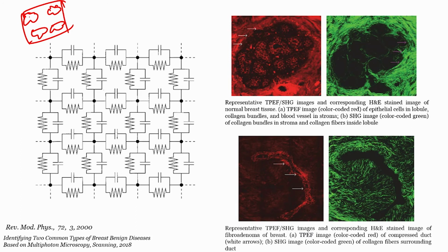You would agree that this conducting island can be considered as a finite resistor element, because it can be considered as an analog of a metal wire, right? In between there is a non-conducting region. This non-conducting region does not conduct electricity, but it can act as a dielectric. That's why this can be considered as a capacitor in parallel with the network.